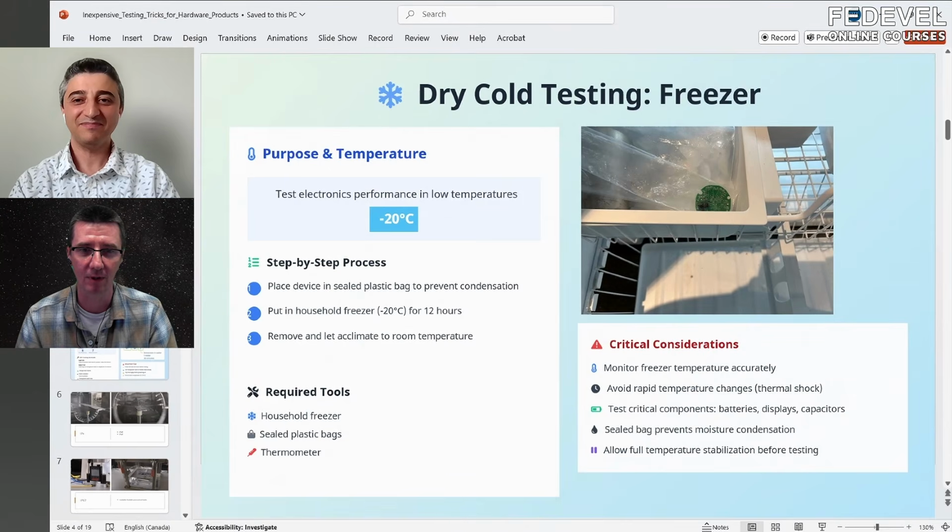But if you go to minus 40 Celsius, that's a 60 degree Celsius difference, and things are going to work differently. Especially what I've seen are problems with memories, problems with oscillators, and maybe startup, like booting up the board at minus 40. These are the kind of things I've seen, and they really can be problems.